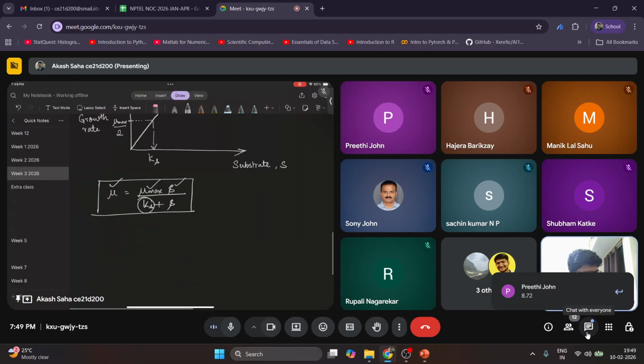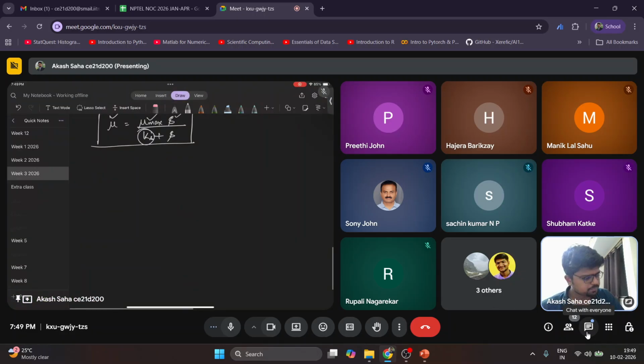So how did we get this? This is question number 11. First we will calculate the surface area. Surface area will be nothing but the discharge divided by the SOR, surface overflow rate. Discharge is around 720 meter cube per day and overflow rate is 16.5, so we'll get something around 43.64 meter square.